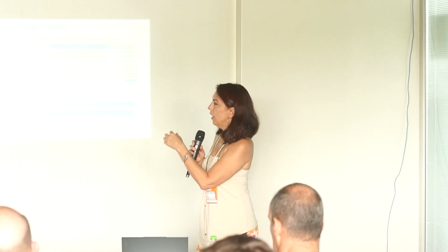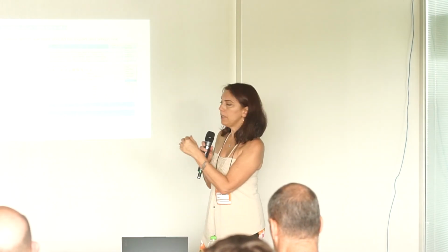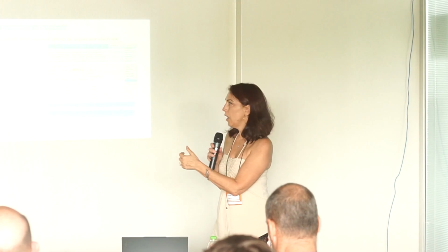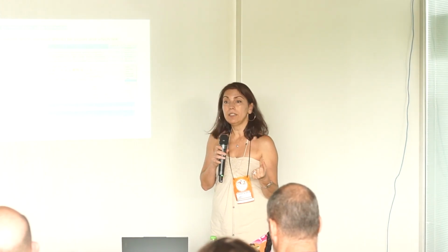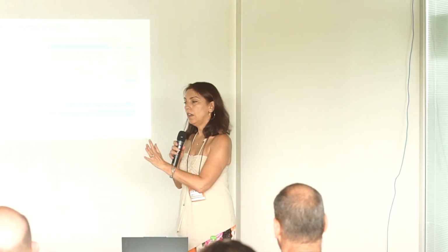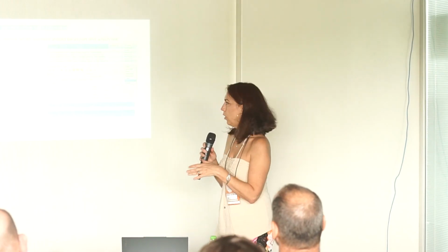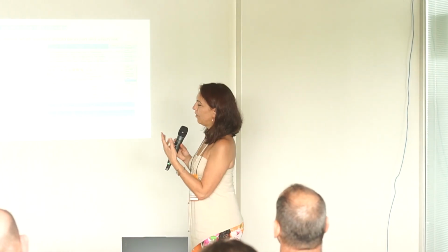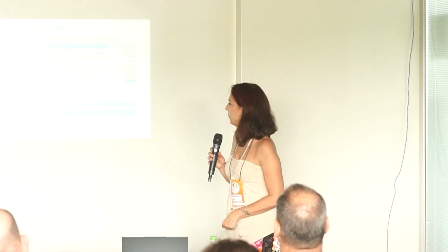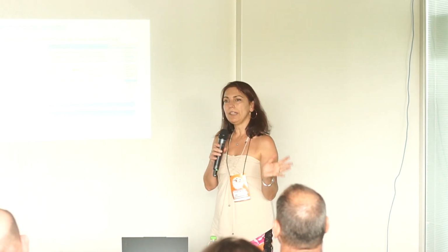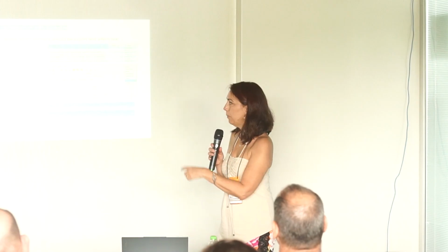Besides the EPA types that Epanet or SWMM needs, you can also say undefined. These will be the elements that will not be brought to the EPA type, to Epanet or SWMM. Then there is another nice way to choose what is brought or not, and that is the state type.